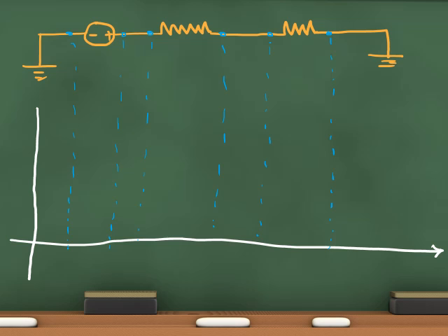We know that the ground is at zero potential, that is a standard notation. Say the battery is at 10 volts, and at this point it is at 10 volts. So there is a voltage rise across the source, and it maintains the same level up to here, but the resistor will drop the voltage to some level, and it will maintain the same level up to R2, and again drop.